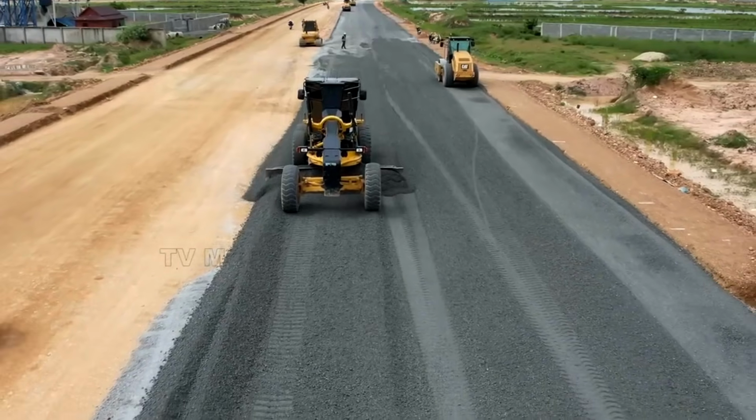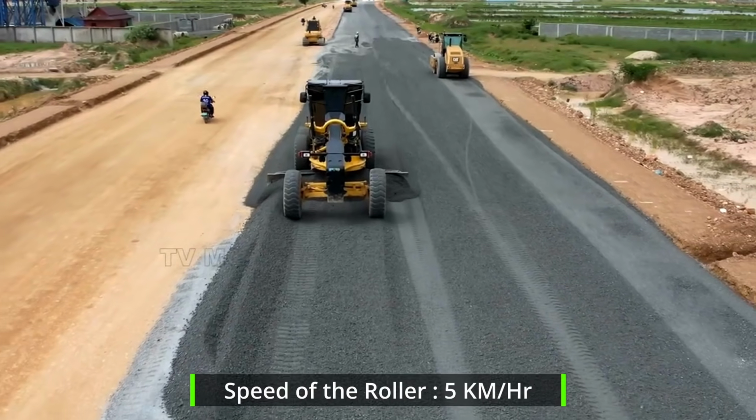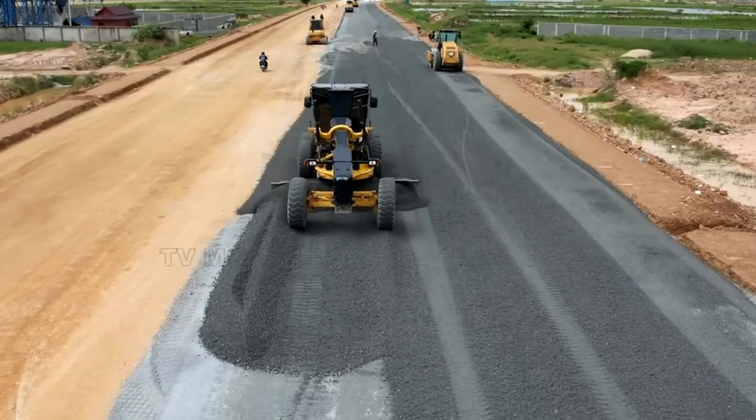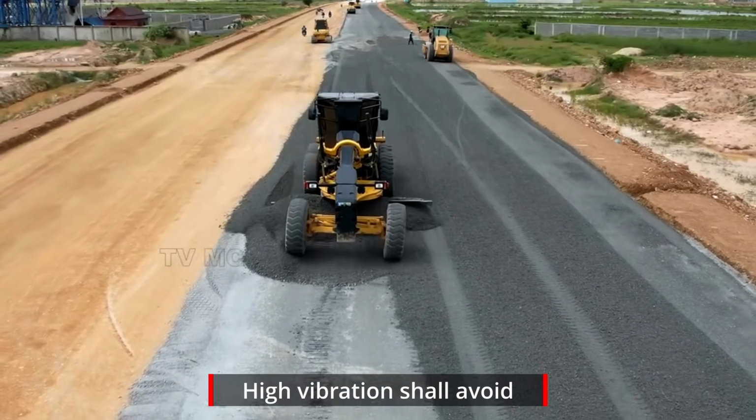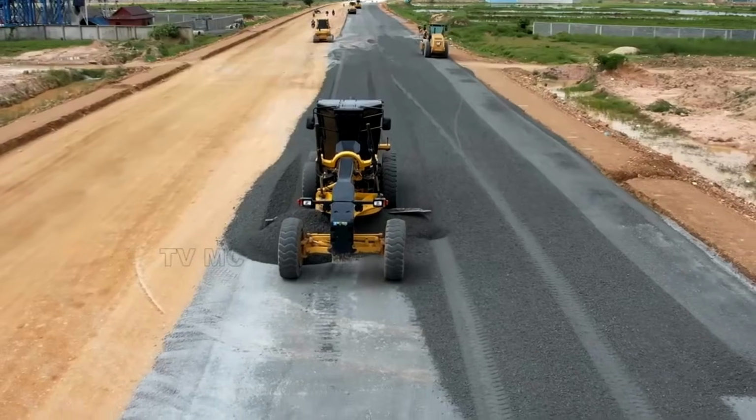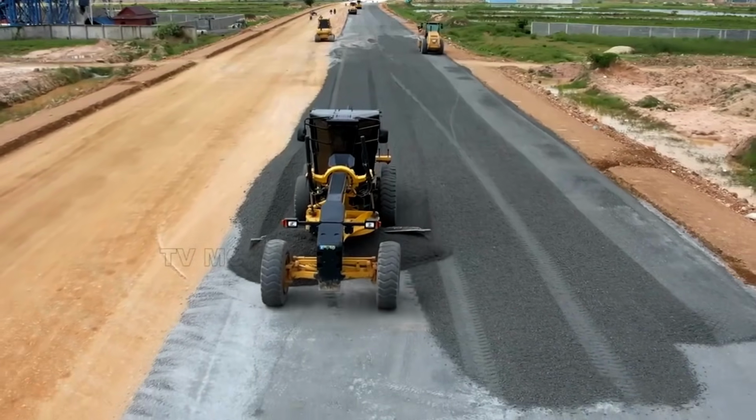The speed of the roller during compaction shall not exceed 5 km per hour. Generally, high vibration passes are avoided in wet mix, as they may crush the aggregates, which can reduce the durability of the pavement.